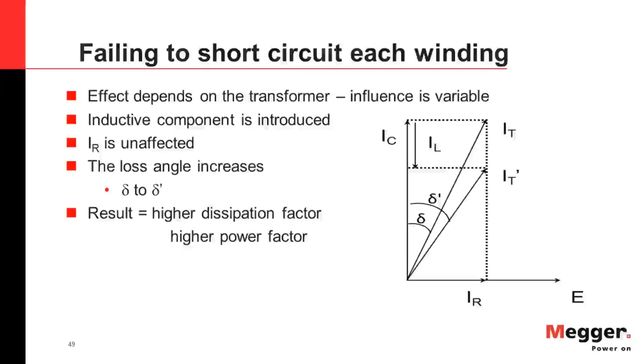So we'll move on to the next category, which is test voltage, and have four slides of do's and don'ts related to test voltage. The first being, don't be lulled to sleep when test voltage is selected for you by the software. Typically, industry standard test voltage will be automatically provided nowadays once you, the user, provide the winding ratings and configuration of the transformer.